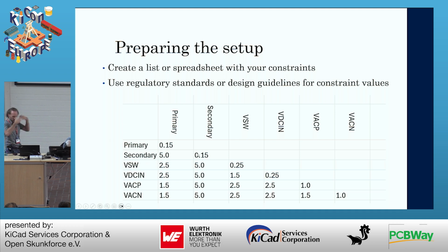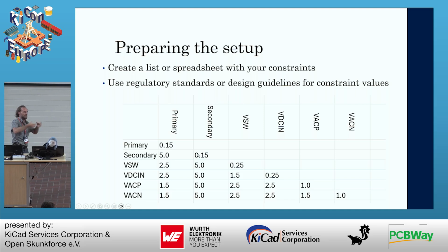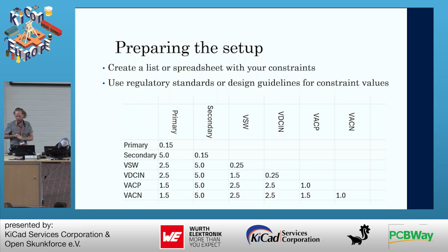And the secondary to secondary, that is signals within the secondary net class, I set that to 150 micrometers. And for the switching node on the primary side, to the primary voltages, and again, primary is the net class called primary, I set them to 2.5 millimeters, and so on and so forth. We fill in all what we find relevant. We got some numbers down here. And when I've done that, then I have the numbers that are relevant to move forward with the design.